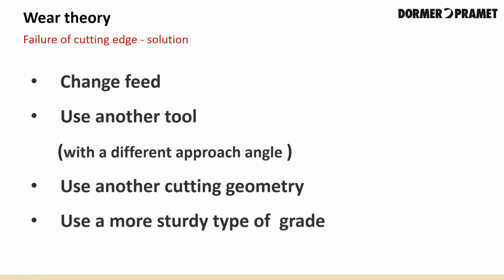We can try to diminish the effects by changing the feed. We can use another tool which has a different approach angle, or we can use another cutting geometry, or use a more sturdy type of grade.